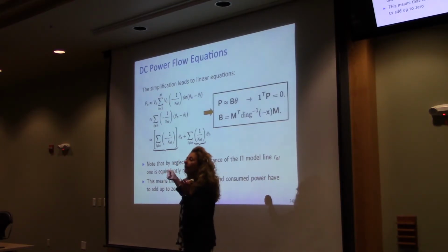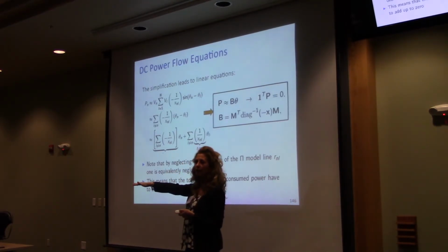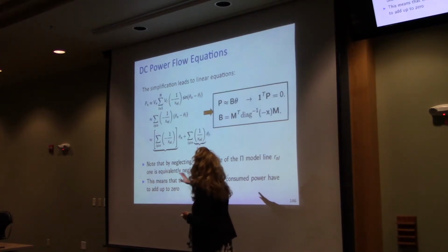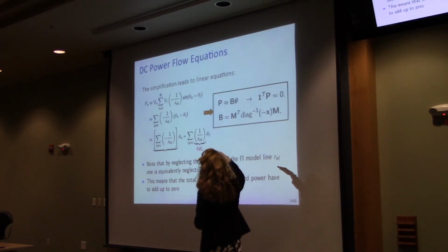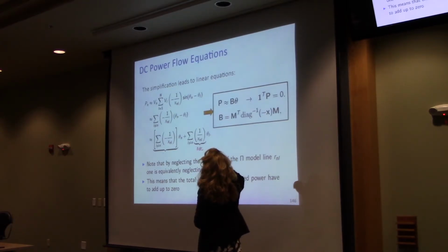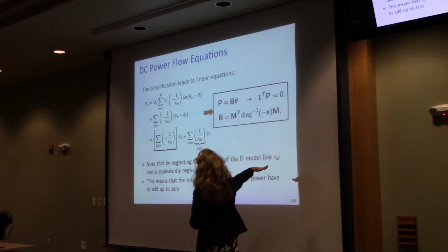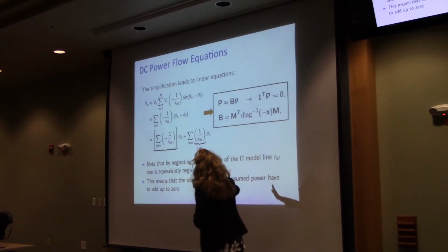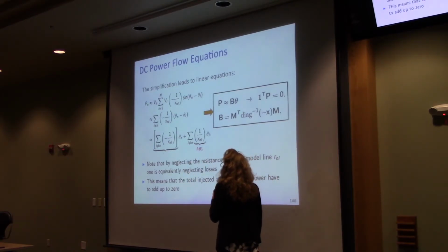And you use a surrogate for your voltage phasor. You say the voltage is constant, right? You actually normalize it to be 1 because you know at what level of voltage you are in the network. You can renormalize everything. All this normalization is called per unit. So you represent everything at the same voltage level. You say that therefore the voltage amplitude being constant is 1. And all you do is now you focus on this phase angle difference, which is now the state of the grid. And now you have linear equations.